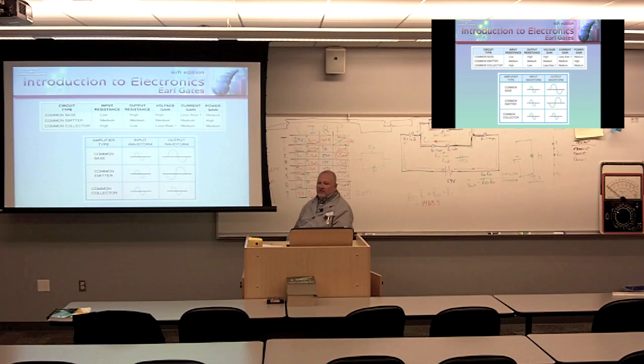So remember that slide where I said common emitter is the most popular configuration? This is why. Plus it's got medium input impedance, medium output impedance. It just lends itself to most applications.